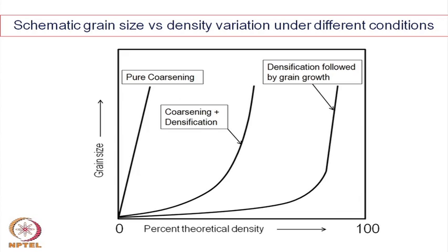There you need larger pores, or finer pores in large numbers, but at the same time you need strength. So you have to make a compromise between densification and mechanical strength, so that the material can be used as a high strength membrane or porous material. So, 100% densification is not always preferred, particularly for membranes, but otherwise very close to 100% densification is certainly a preferred situation.